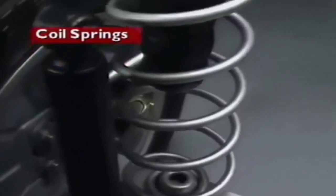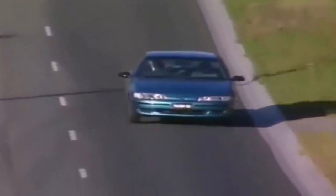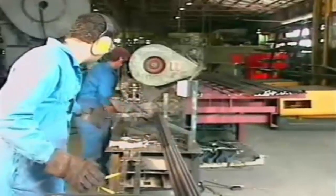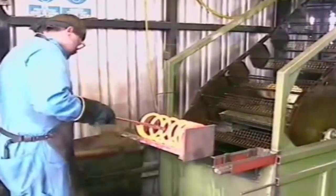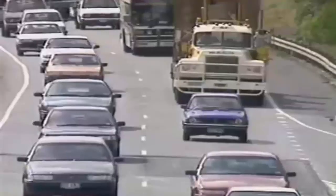This section examines coil springs. Coil springs are used on the front suspension of most modern light vehicles, and in many cases they have replaced leaf springs in the rear suspension. A coil spring is made from a single length of special wire, which is heated and wound on a former to produce the required shape. The load-carrying ability of the spring depends on the diameter of the wire, the overall diameter of the spring, its shape, and the spacing of the coils. And this also decides which vehicle it is suitable for.